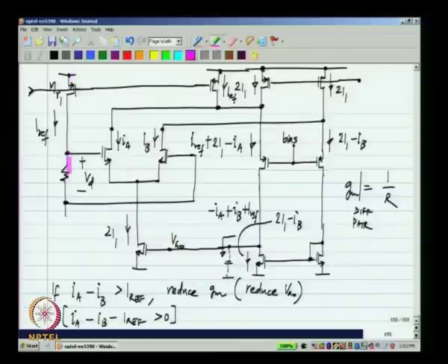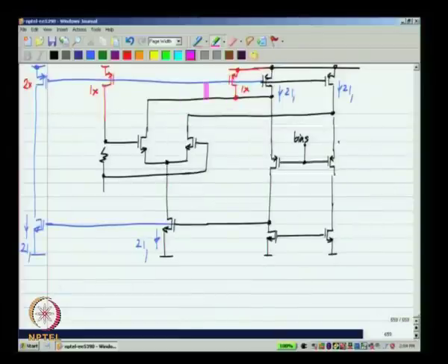the current that is injected here and the current that is injected here should be matched very well. Okay. There cannot be any error between the two, because finally we are relying on this current being exactly Iref for the negative feedback to settle to the correct operating point. So, we may have to use accurate current sources here. So, it could be that you will use cascodes. Okay. So, in this particular place you can use a cascode arrangement instead of a simple current mirror. Okay.